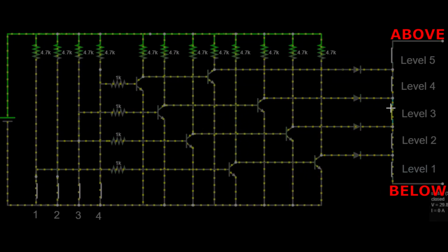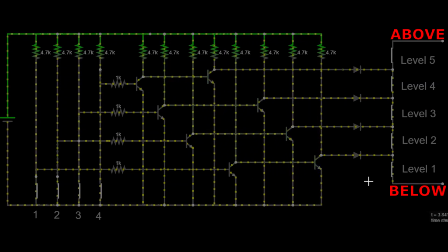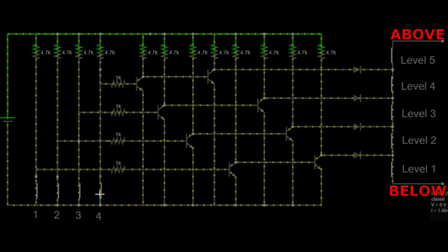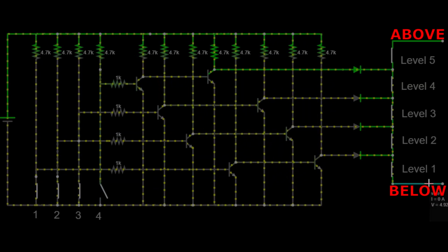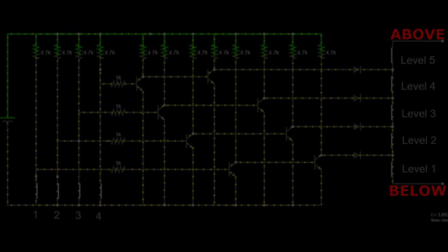So as you can see from this, that's the basic logic behind the navigation. There is a separate logic behind the actual direction control of the motor. That logic is based on determining whether there are calls waiting above or below, and it will travel in one direction picking up calls until there are none left. Then it'll reverse and go in the opposite direction picking up calls until there are none left. It will keep doing that until there are none left at all. So that's the basic logic behind that. So the next thing we'd need to look at would be the actual motor control aspect of it.